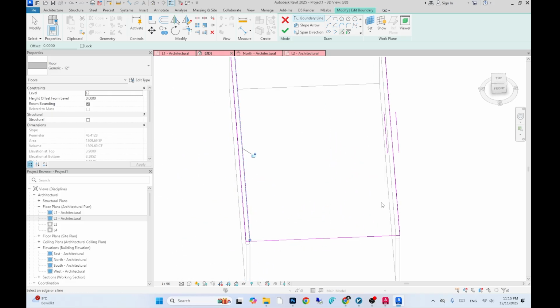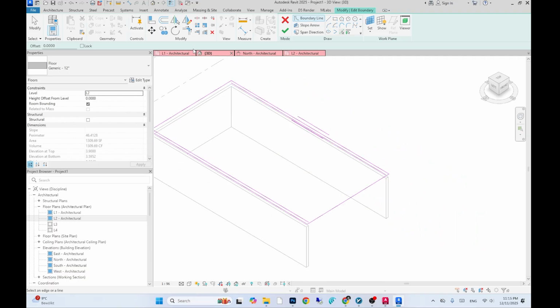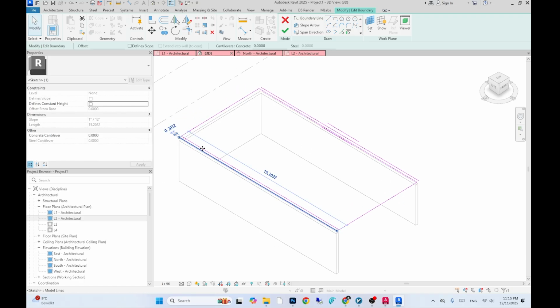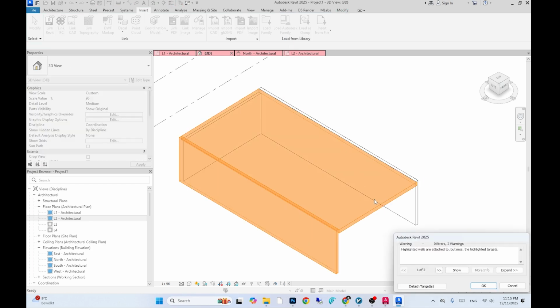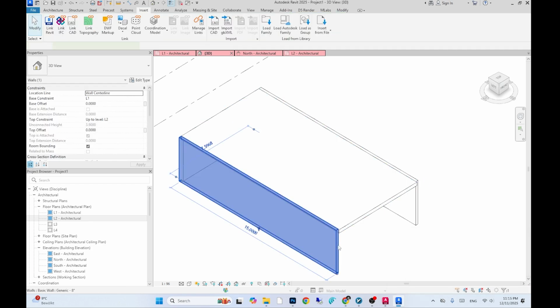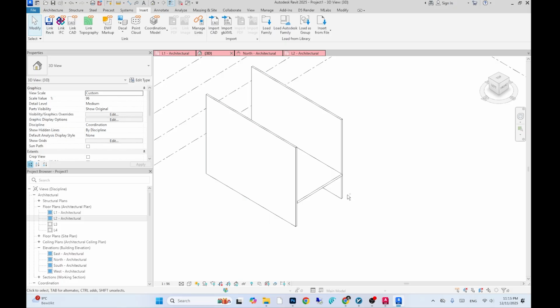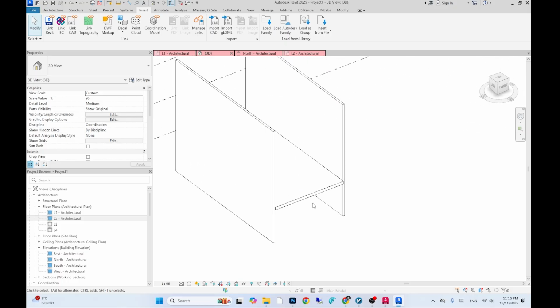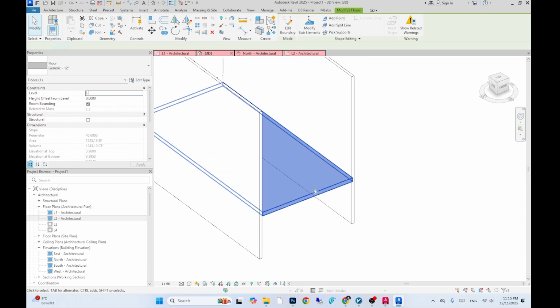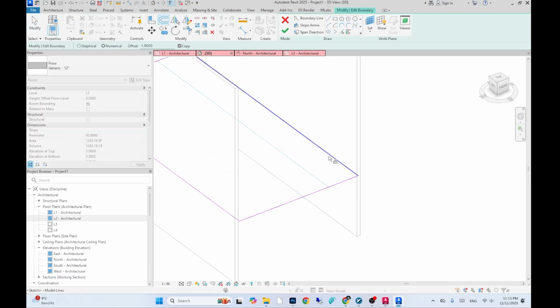I'm also going to do one extra step here. I will extend the slab inward by the same thickness as the wall. So we end up with a single continuous wall all the way up to the roof, similar to what you see in the reference map. Normally, we wouldn't do this in a real project, but since this is just for visualization and the simulation, it's totally fine.